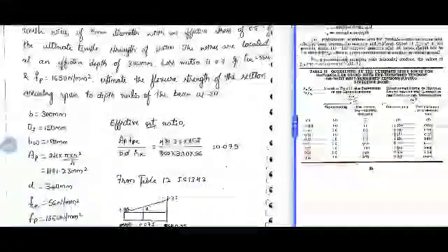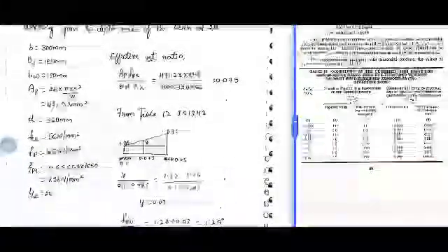So first step again it is same, effective reinforcement ratio and L by D ratio. Since it is unbonded case, but L by D ratio is directly given, it is 20. So directly you keep the value and calculate effective reinforcement ratio AP FPE by BD FCK. So FPE, effective stress, it is not given, we need to find out.